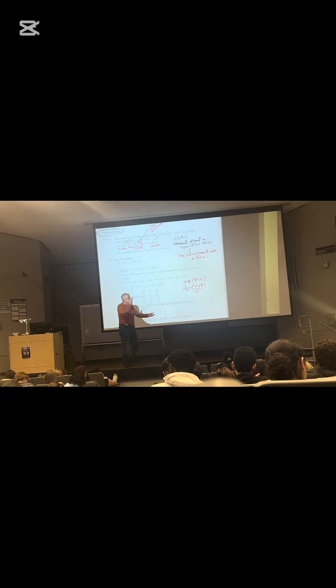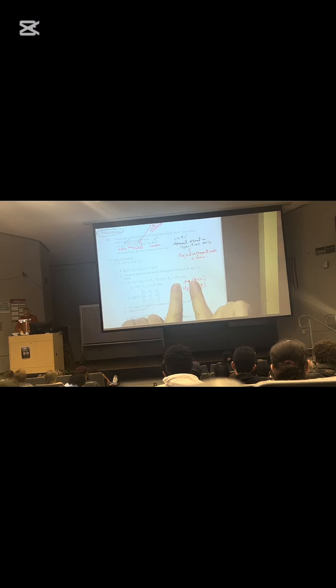It's an application of the dot product, where the vector happens to be a moment rather than a force. That's it. How do I calculate a moment? R cross F. That's it right there. R cross F, and then you project it onto this line by dotting it with the unit vector of the line. Easy peasy.